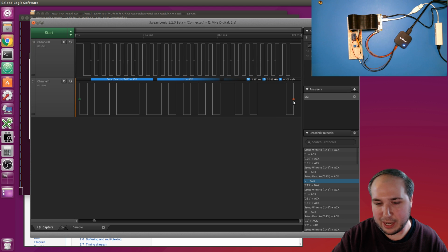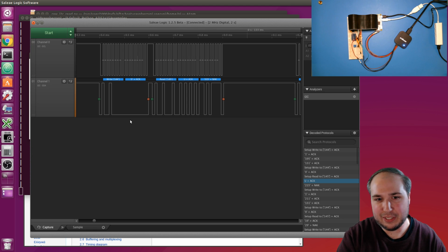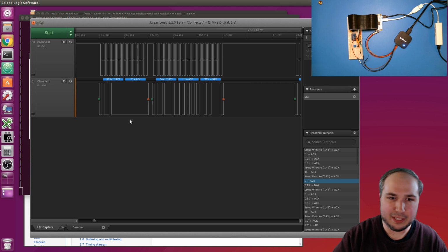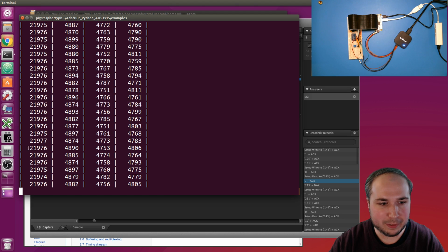And then it sends the I2C stop bit again here, where it lets the clock line go high and then the data line go high after that to acknowledge the end of that. So what's happening in these 2 transactions is we're reading the ADC value. To do that, we first do a write to say, here's the register I'm going to read, and then we do a read of 2 bytes because it's a 16-bit register, and we pull down those 2 bytes of data. And then my program can interpret that raw value to say, okay, I need to do a 2's complement conversion on this, and basically turn it into a signed integer value. And that's what we see when it's printed out here.